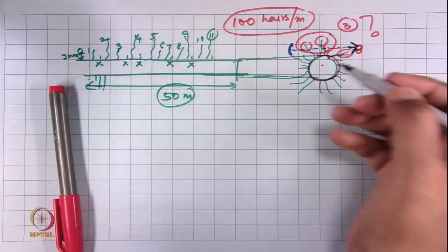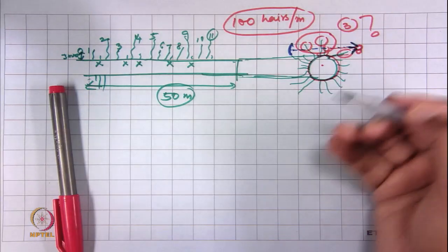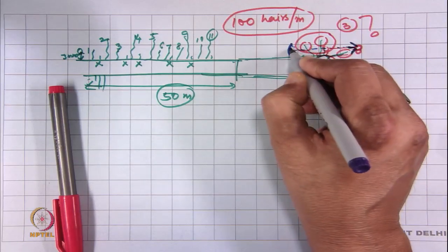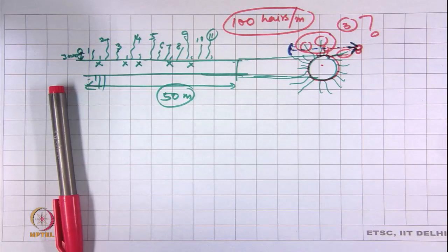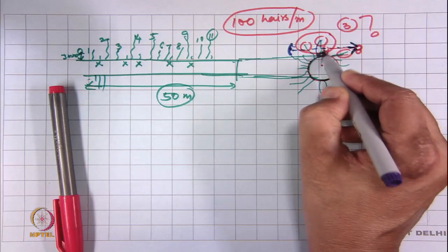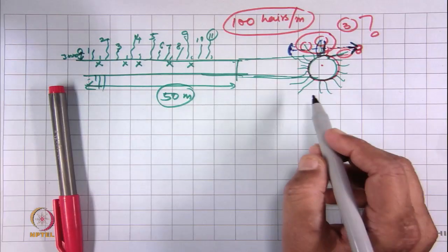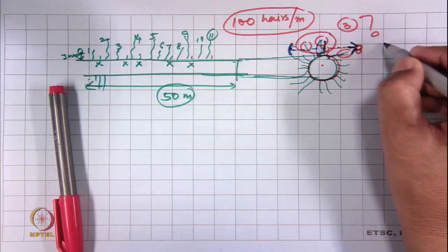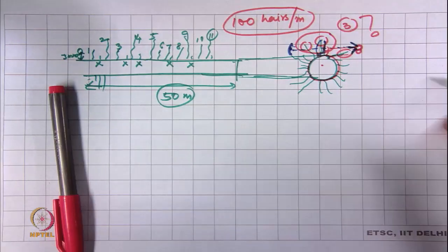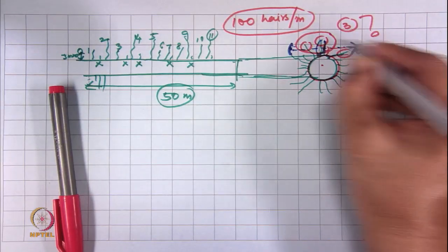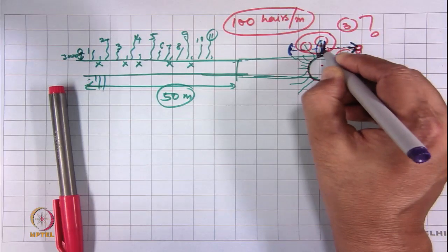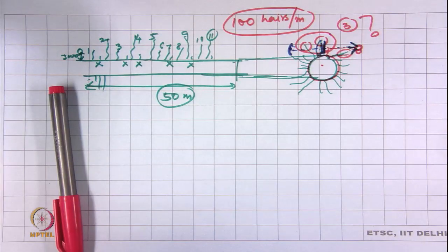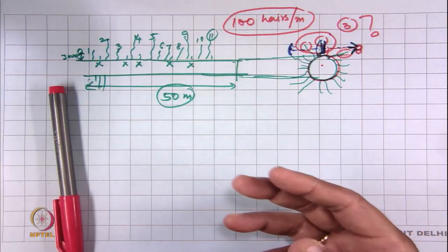Now, while the yarn is moving, if there is no hair, this light will totally reach the photoreceptor, but in case of hairs coming in between, that obstruction will give an indication that there is one hair. Now, another problem here is that with very high density hair concentration, if two hairs come together, this may give the signal of one hair, but in any case this gives a rough idea about the number of hairs.